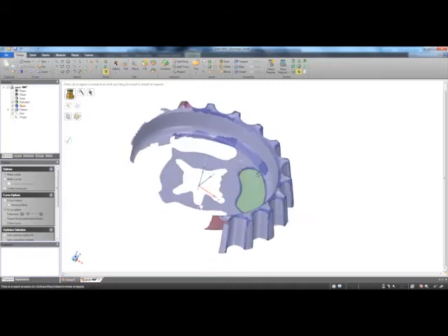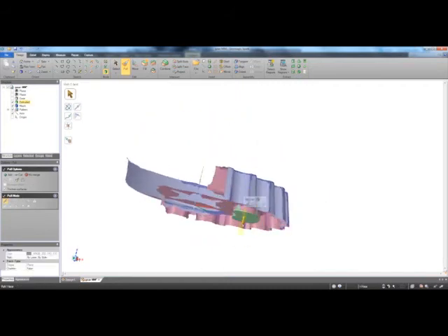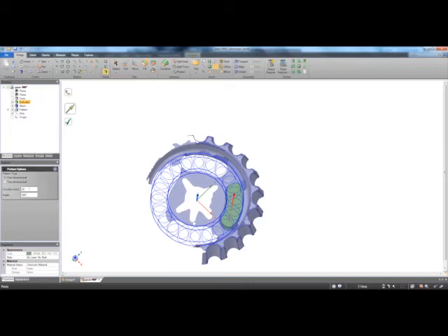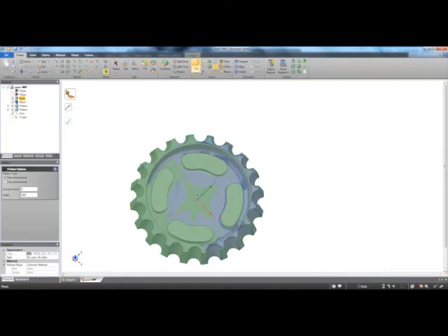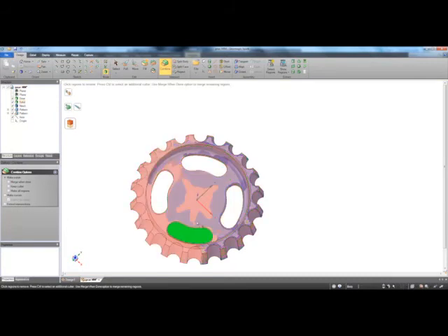And so now you'll see a solid body there. Again, if you go to pull, grab that top face and this bottom one just to make sure they've been overextended. Go to the circular pattern, choose that extrusion, choose the Z axis for rotation, change this number on the left hand side to 4, say complete. I'll show my gear, and again I'll use combine, and I'll choose the gear as my main body, and then that pattern as my cutter.